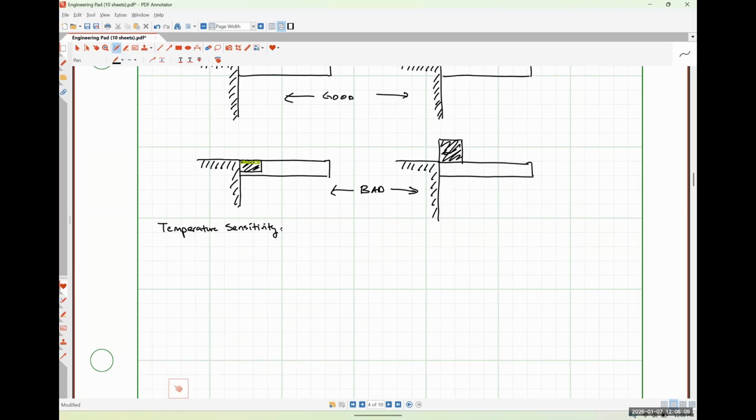So for doping concentrations less than 10 to the 17 dopants per cubic centimeter, which is the value that we used as the constraint in our table for when it's valid.